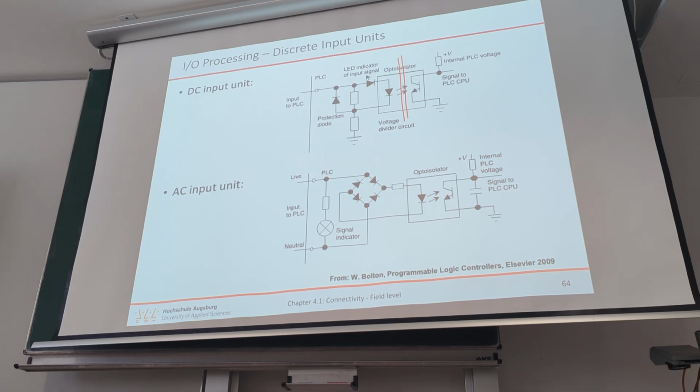And then the next question would be, why 4 to 20 milliamps and not 0 to 20 milliamps? The first 4 milliamps is actually the current that the device can use itself, and then it modulates the remaining 16 milliamps. If you calculate that, with 24 volts maximum and 4 milliamps, it's a very low power device.